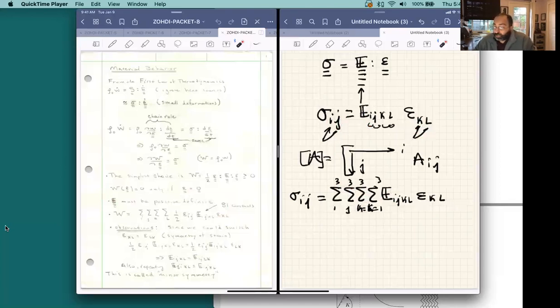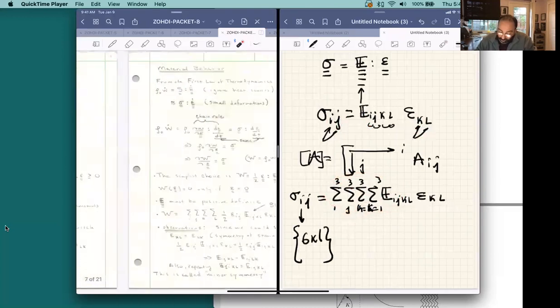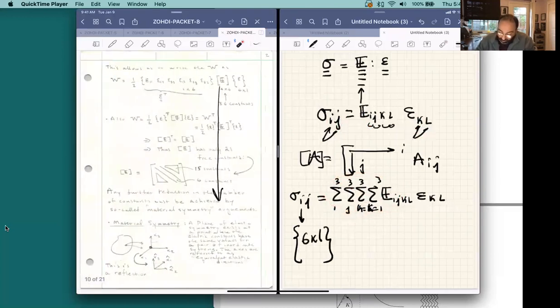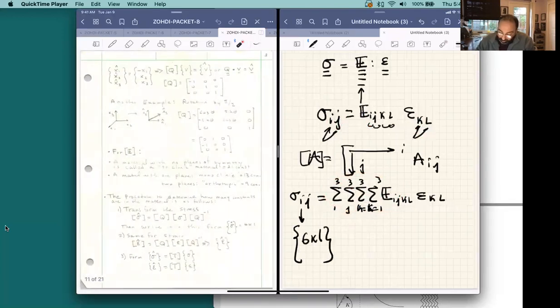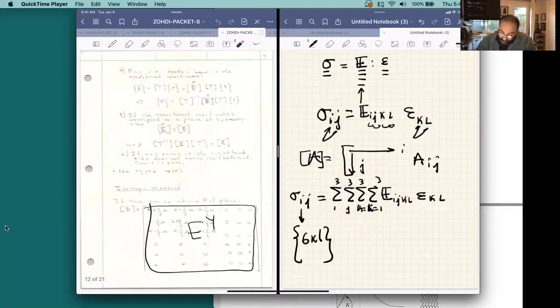People like matrices. They don't want to necessarily write out every time they need to multiply something out with 4 summation signs. So what they do is they say, you know what, let's exploit that this is symmetric. So in fact, this is going to be a 6 by 1 vector, which is basically shown there as a vector here in the relationship somewhere along here. Let me see where it is. Just a moment, written it out. Yep, so it's a 6 by 1.